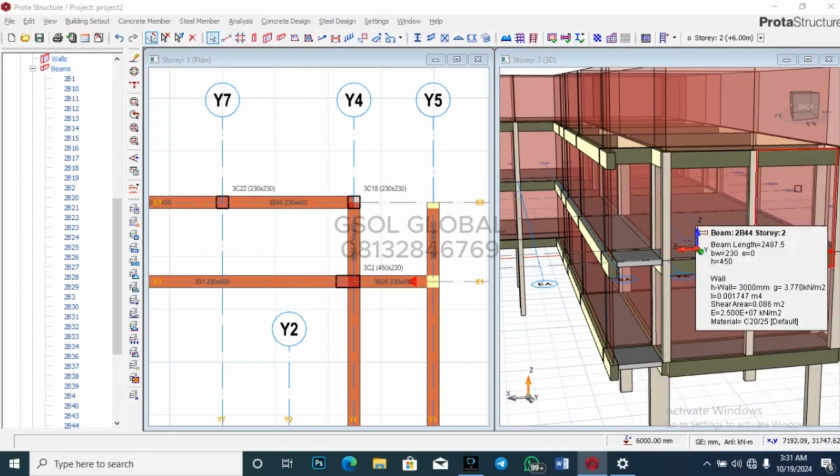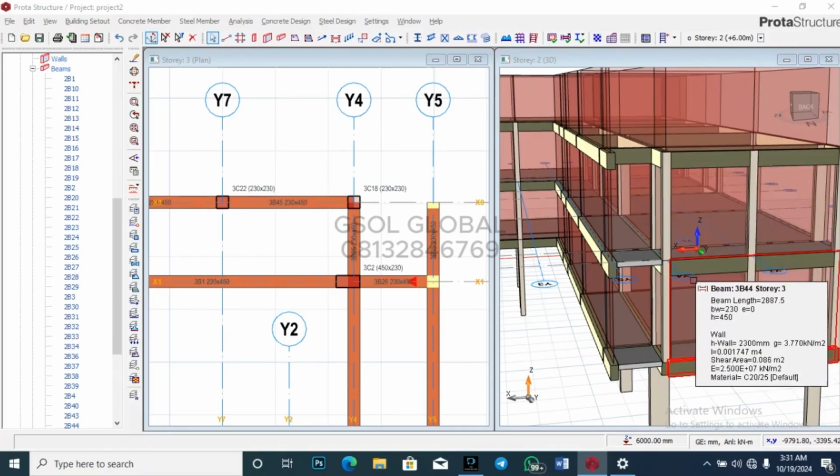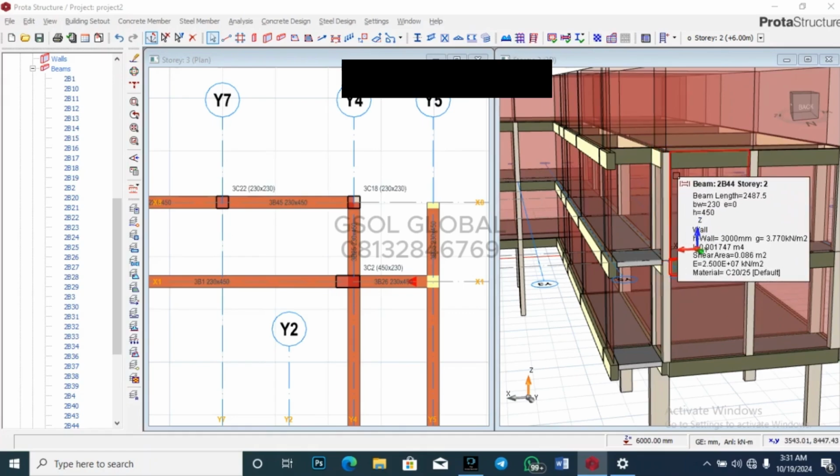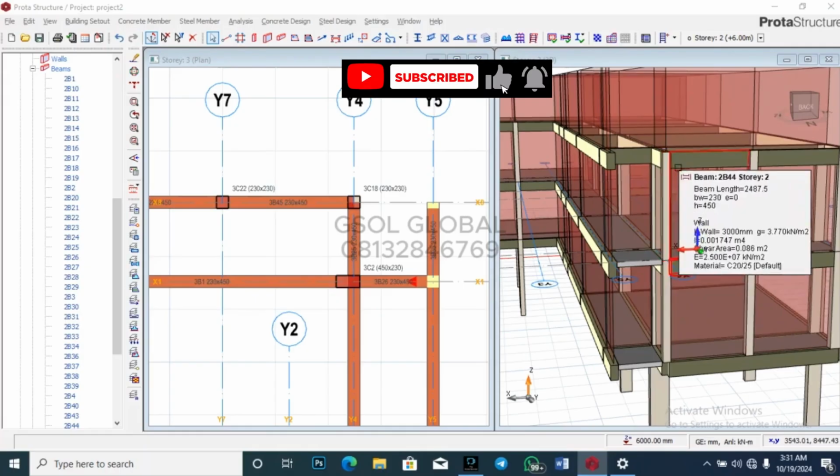It's a buckling, the load is pushing towards the left hand side, because we resolved the right hand side. No matter the moment, the buckling on that column will not be caused by the load coming from the right hand side. It should be by the left hand side. So let's increase the column size towards the left hand side. We'll get our results. Let's see.